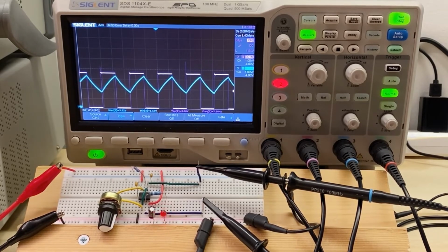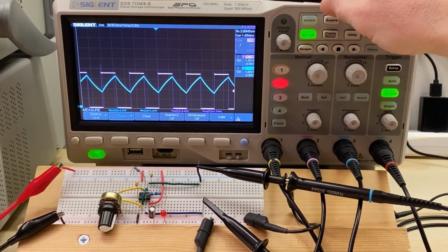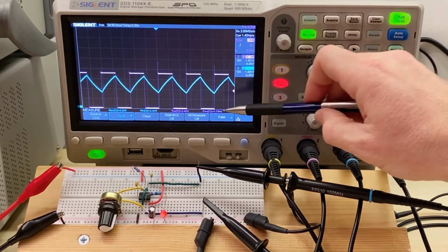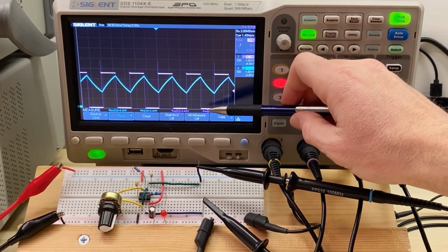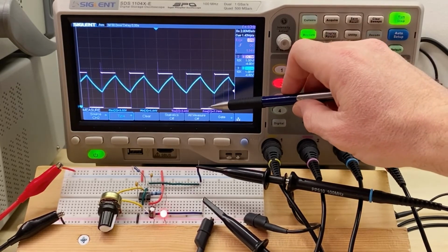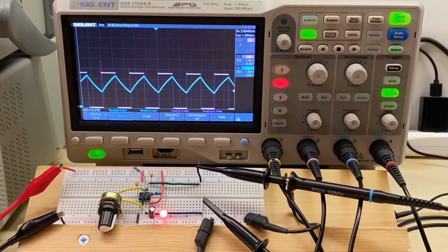And because of the BJTs and how they function, they have difficulty going straight up to 5 volts. In the CMOS versions, they go from 0 to 5, nice and easy. But because of the BJTs, they don't do that, and so the logic is kind of skewed downwards. You know, it's easy to get a ground at 0 volts. But our high, even though our supplies are at 5 volts, they can't quite get up there. And so that's something to keep in mind, especially if we're using HC chips in the future.